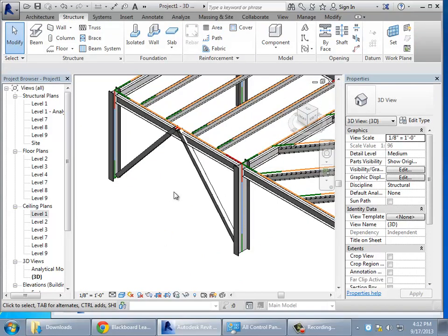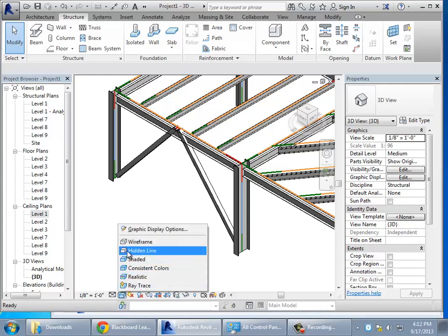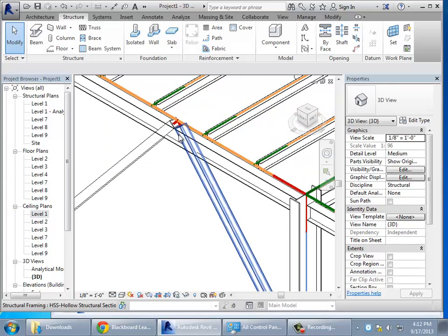Now, you will look at that and say, wait, that looks pretty good, but it's not looking all that great right up there at the top. Let me kind of put that back to just line so you might be able to see it better. Because it's got the brace kind of running through there, but it's a little rocky right there where the connection is. It doesn't really look like a good welded connection. We can adjust that and hope to get it to the point where it's actually true fabrication detail. Then the first pass, this is probably close enough to get you going in terms of understanding where those braces are. It's going to analyze properly. There's a whole next step and some add-on tools that really help you do good bolted steel connections. Make that right.